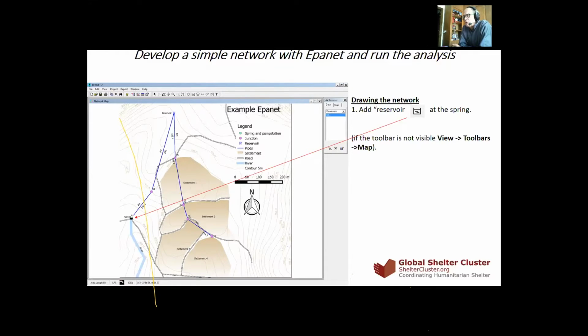And as well, when you do your background map, you have to activate the names of the junctions, the pipes, the tank, and the reservoir, so that when you insert them, you can type the right name as in your Excel file, so you don't mix up the elements. In GIS it's easy to display the names. In AutoCAD, it's also easy, but maybe a little bit more complicated, at least for me.